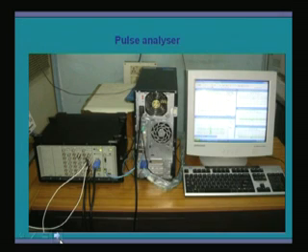Once we have captured the signal from the various instruments, it goes to the analyzers. This is the analyzer, because whatever signal we get from the sensors is analog in form. So if we want to further process those data, we need to digitize them. For digitization, this is the A to D converter, and apart from that, it conditions the signal, because some noise is there. Those unnecessary noise it eliminates, and then it digitizes in the computer hardware.